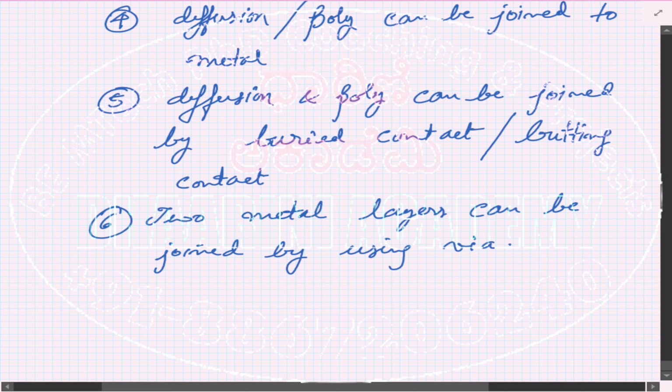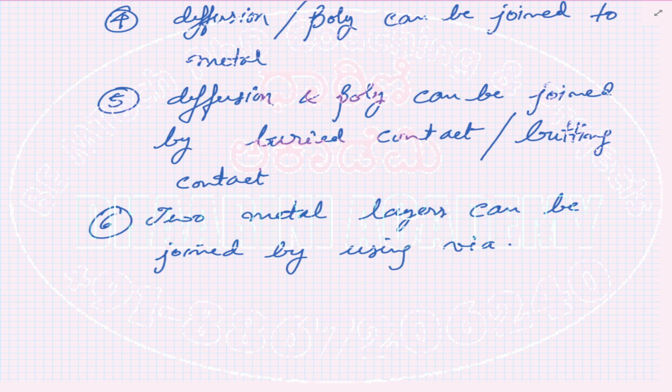Okay, and coming to the CMOS, complementary MOS architectures, if you have NMOS and PMOS diffusion wires, they should not cross N well and P well because there is a boundary limit for that. Anyway, we know that it never happens, but I just mentioned it here. And electrical properties of each layer should be taken care of. Maybe one of the layers is more conductive, another creates more magnetic field, some properties will be there. You need to take care of them before you use them as a layer in your design.